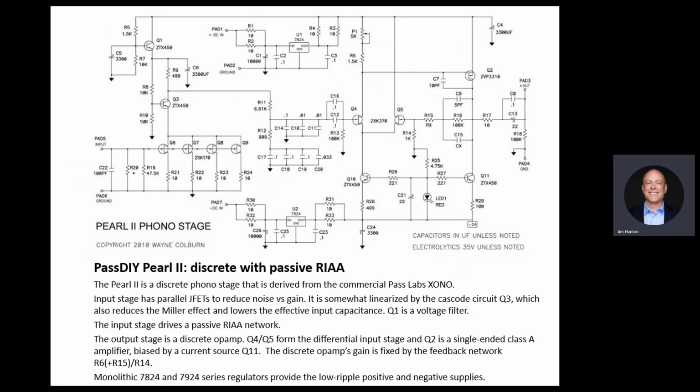So when we look at it, there's a capacitor here, 22 microfarad electrolytic. Okay, I don't like that. So we put a DC servo around it. These are series regulators. We talked about them. We changed them to shunt regulators.